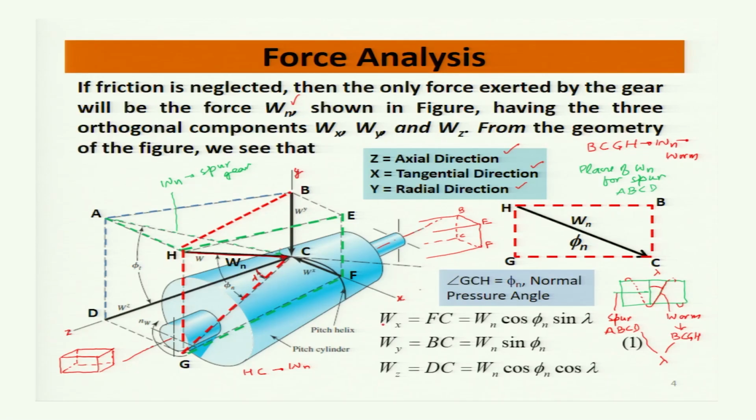Whatever force will act in the direction of Y will be the radial force on the worm, and whatever force will act in the direction of X will be the tangential force, and whatever force will be in the direction of Z will be the axial component.